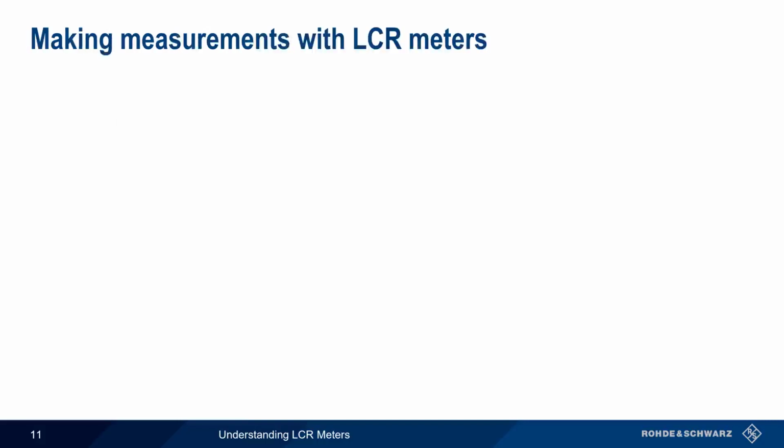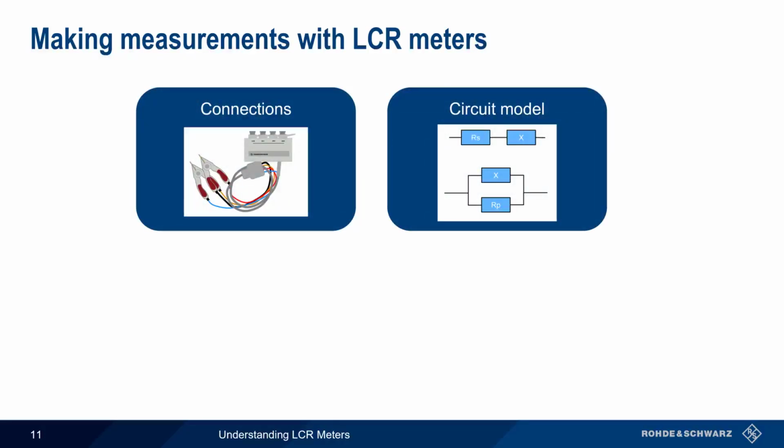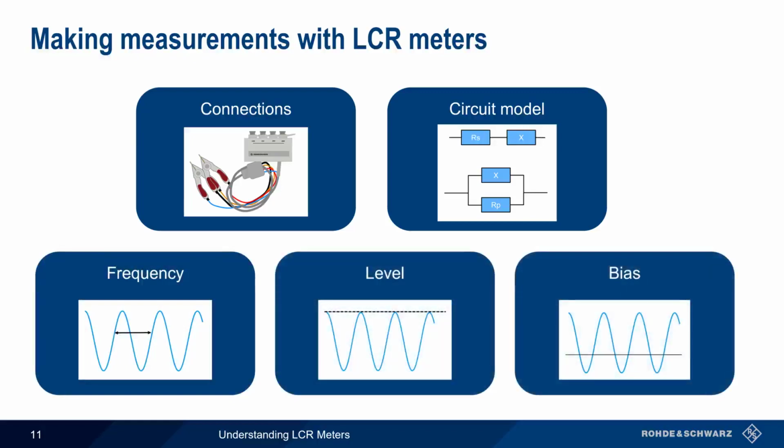Now let's look at some of the more important topics when it comes to making measurements with LCR meters. These are connections, circuit mode, measurement frequency, measurement level, and bias. We'll start by looking at connections.